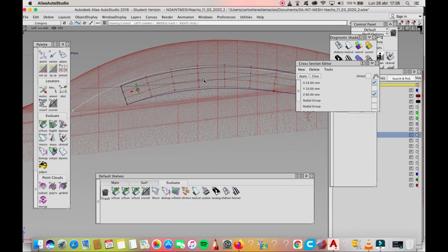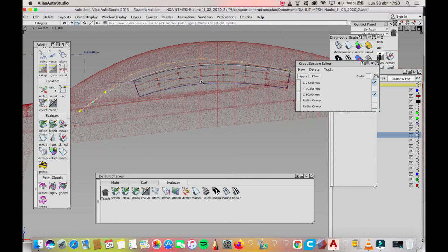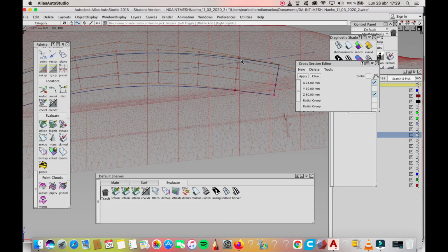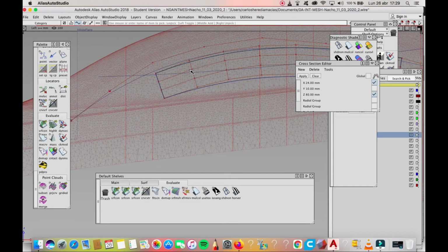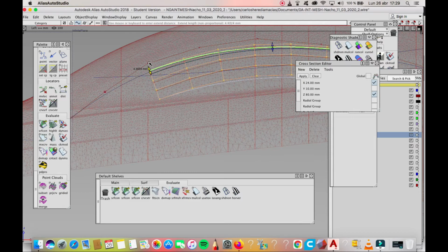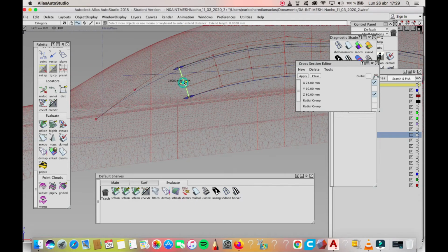We can go and shape this curve a little bit down so everything is inside the surface. As you can see in this area, if we trim, the surface goes beyond a little bit, so we get this piece inside the surface. Or as I've done, I can go and extend the surface this way, for example, a little bit, so my curve is inside the surface. And here I will have to do the same, extend it a little bit.